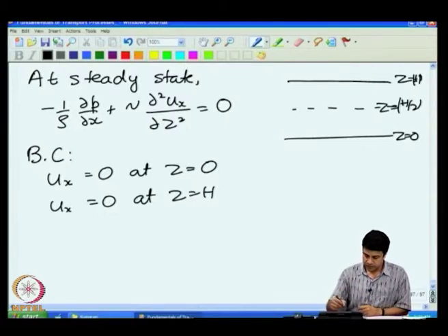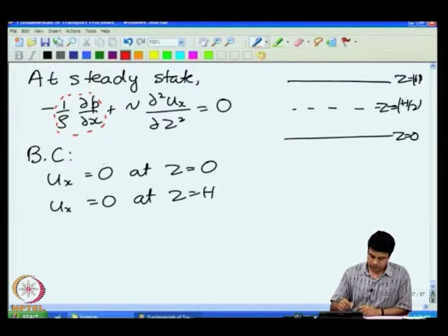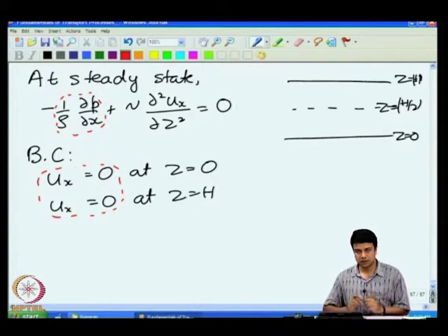Note that once again, this is an inhomogeneous equation; it contains an inhomogeneous term here. So, there is no forcing at the walls. The velocity at both the boundaries is identically equal to 0, so both the boundary conditions are homogeneous. However, there is a steady forcing within the equation itself due to the pressure gradient that is applied across the length of the tube.